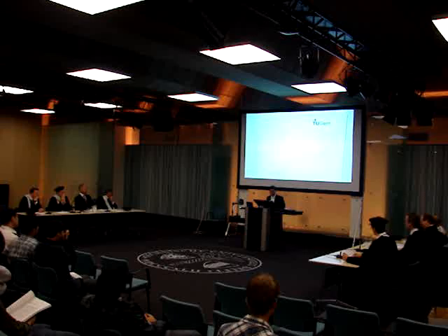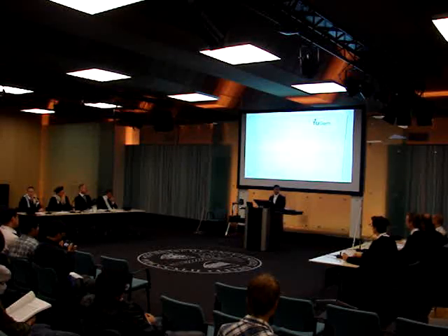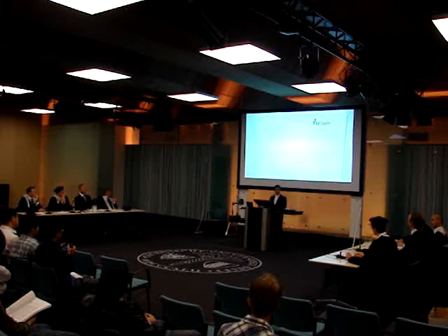Wow. Yeah, I think if you have enough Gauss points distributed along the crack, then you can capture a realistic distribution of the traction profile along the process zone. However, if you have more Gauss points, then the RVE is smaller. I think there's a difficulty there. Yeah, I think so. Okay.